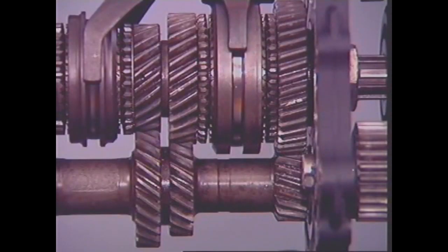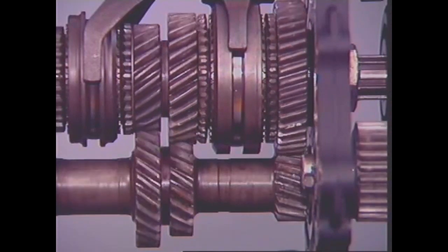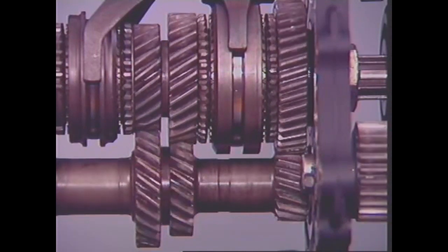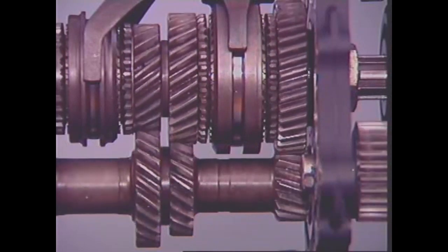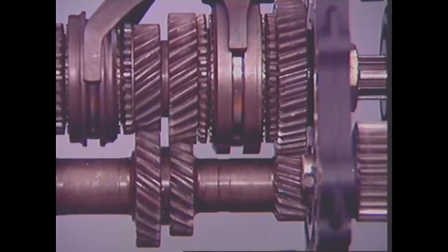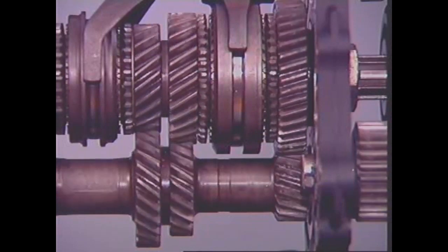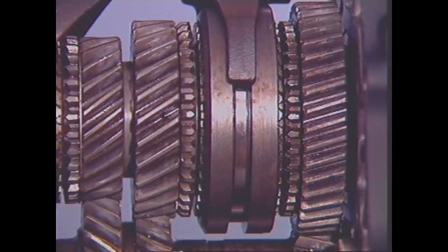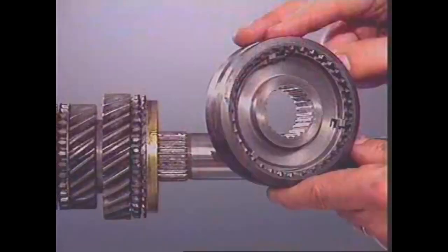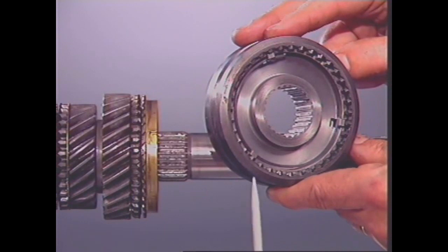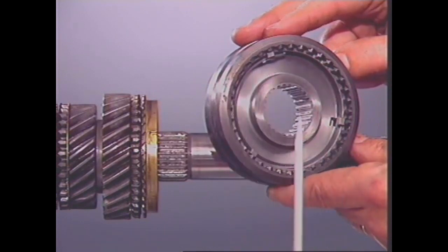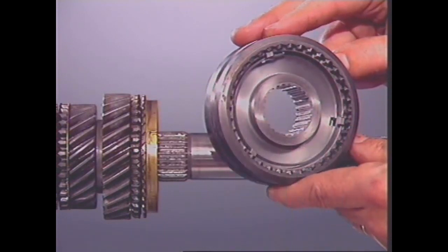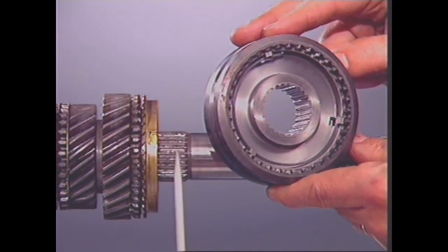These gears mesh with mating gears on the main shaft or output. These main shaft gears are supported on bearings on the shaft. They can rotate without turning the output. Each main shaft gear has an external toothed section on one side. The teeth face an internally toothed engagement sleeve located on a central hub, which is itself splined to the main shaft.